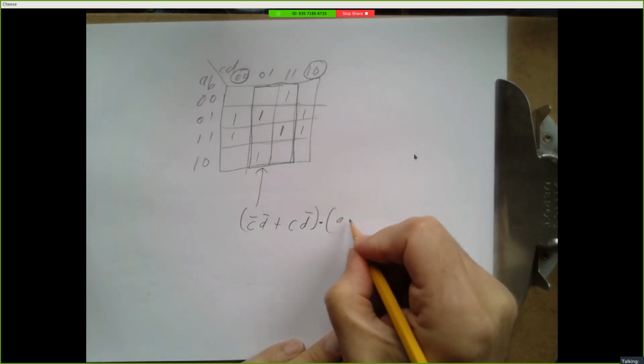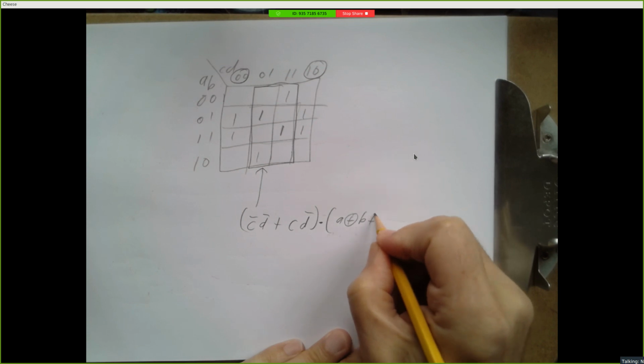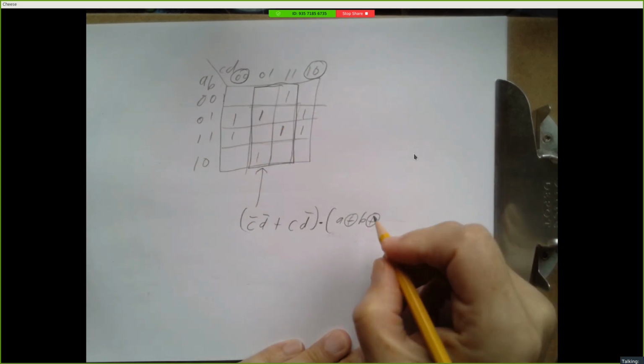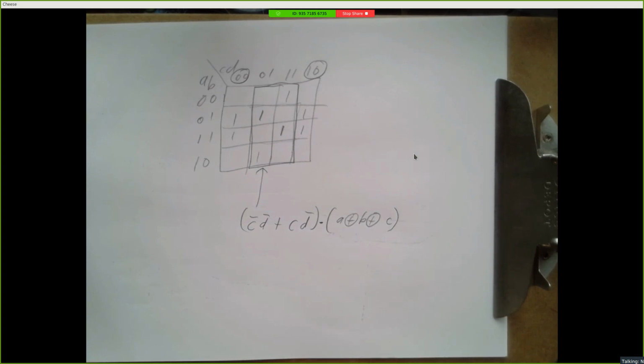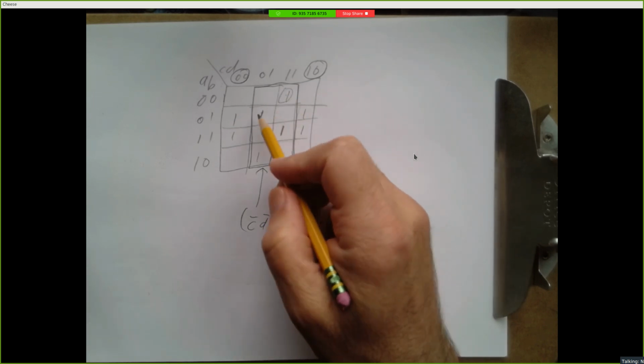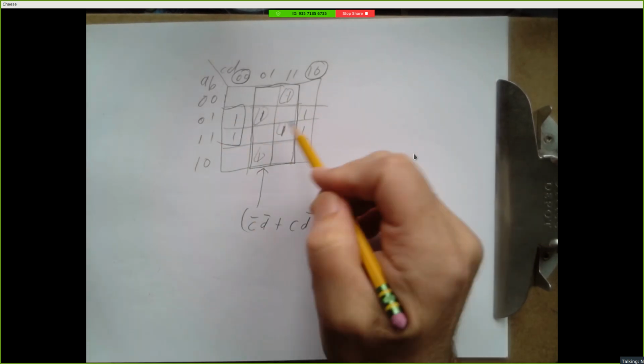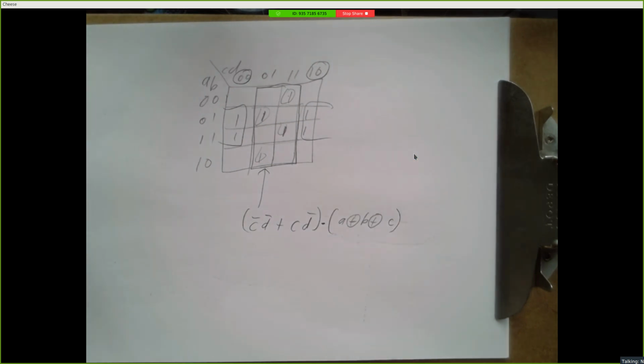I think it's A XOR B XOR C. Right? But that's more trouble than it's worth, because like I say, the only case where you're dealing with a K-map with 4 input variables is if you're trying to simplify that original truth table for 4 bits in, 3 bits out. And for that, you're not going to reduce that to an actual circuit, so I would just do a product of sums, 1 by 1 rectangle for these, and then cover the rest however.